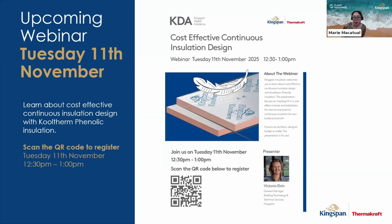Is a staggered insulation board layout or a double layer required for systems like RoofLogic? I would think RoofLogic would be normally following a staggered board layout system, but it might depend exactly what they are doing in that system. But it's a general standard for PIR or any rigid insulation material that the boards are offset in a staggered system to prevent thermal lines going through. RoofLogic has other insulants within their portfolio as well. So they might talk to you about what your limitations are on design and what you need to achieve, and then direct you to the appropriate insulant and layout for your project.